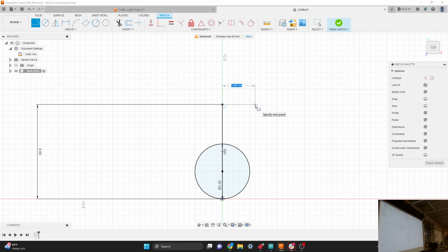Okay, I'm going to put him anywhere I want. I have this point here. So I go to constraint, coincident. I think you've got the wrong point selected already. So hit the escape key and click off into no man's land over here. Now choose your coincident constraint. And then there you go, that point, and then that one. There we go. Cool. I think it's because you already had a point selected when you went to make it coincident.